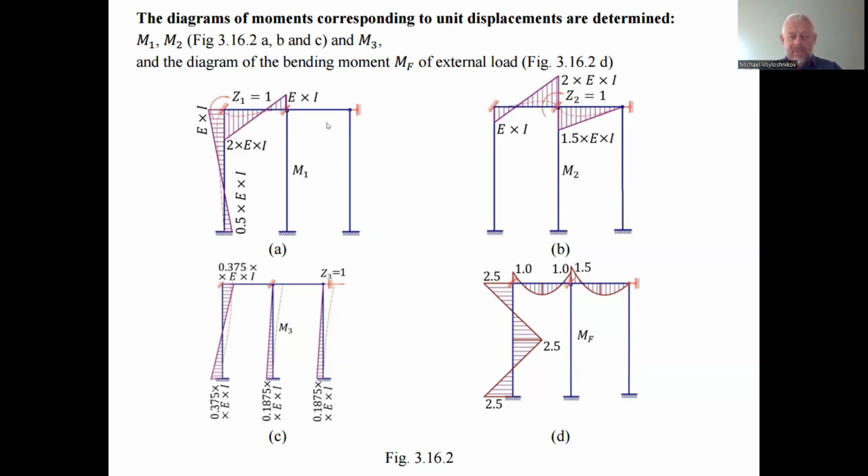So the signs of these two diagrams are interdependent, but usually for a single span two-supported beam, we consider the moments as positive if the diagram corresponds to bending the ends of this single span upward. This will be the positive. It could be another one, but we would not make a mistake, and we have to obey the rules.